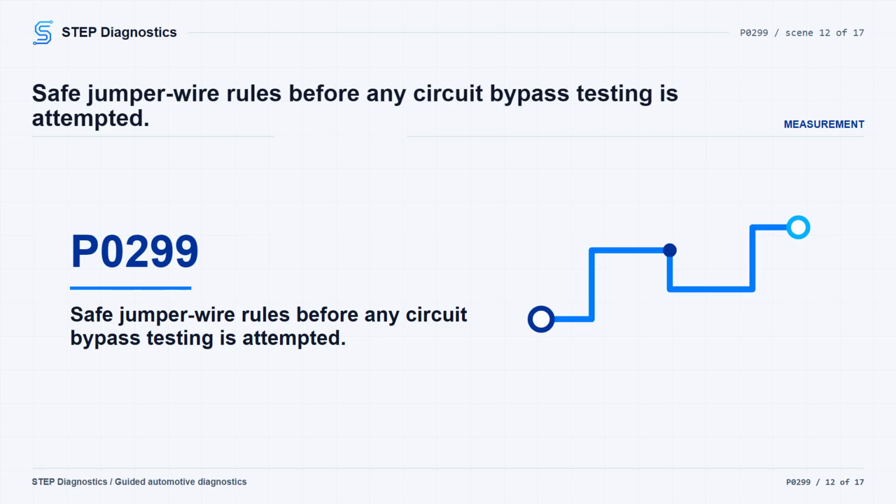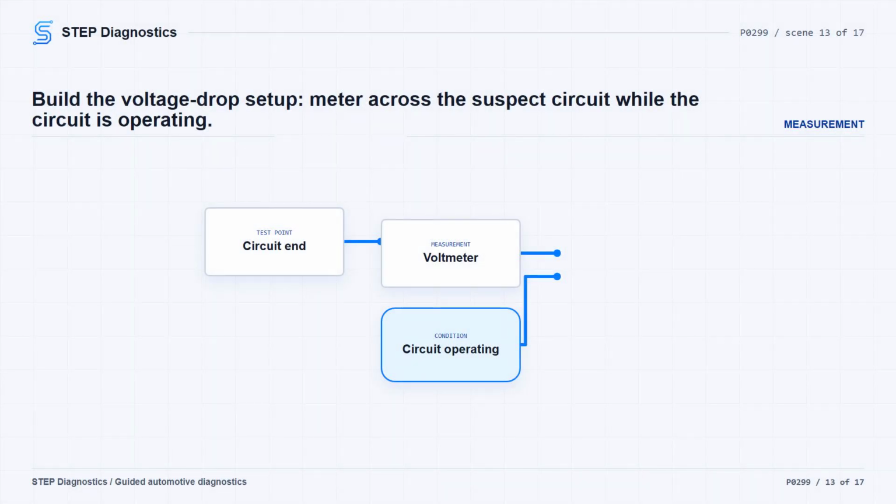Use flex probes or an equivalent method to prevent connector terminal damage. But remember, flex probes are not intended to carry high current greater than 5 amperes. Do not apply ground or power directly to module switched components with jumper wires unless the diagnostic path specifically calls for it.